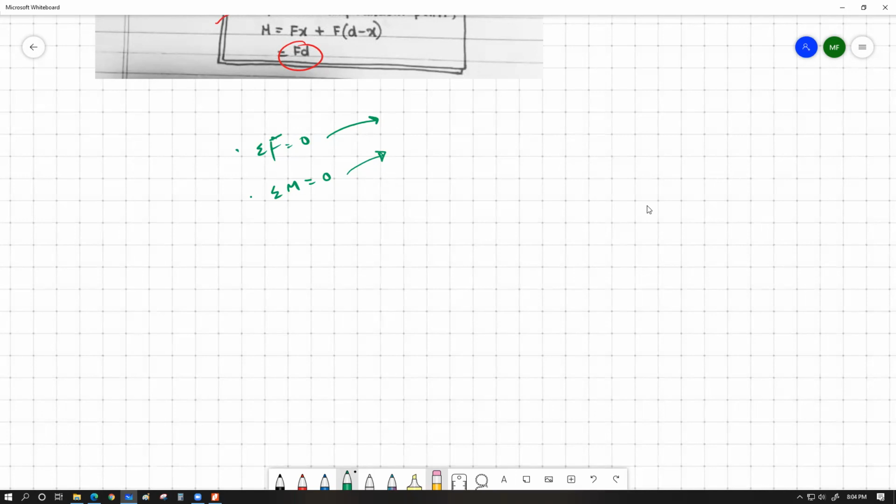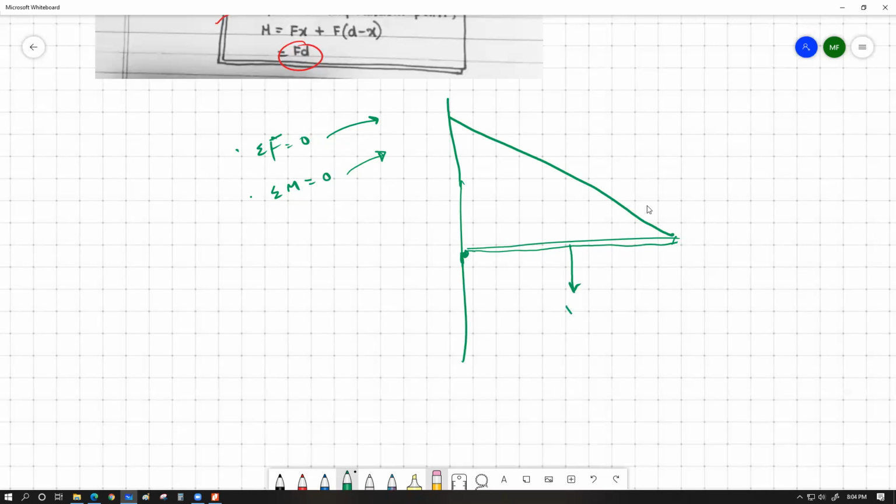One simple example that was given in the worksheet looks like this. Let's say we have a wall and a hinge over here, and with that hinge we have attached a plank. Let's say this plank is supported by a piece of string right here, and the plank has some weight. So this string is producing a tension force in this direction. The weight is working vertically downwards. We are considering a uniform plank, so the weight is drawn from the middle of the object working downwards.